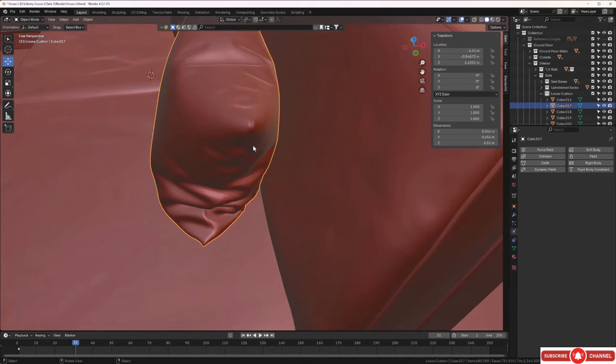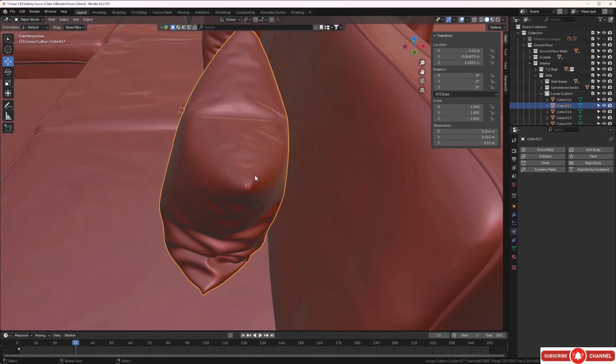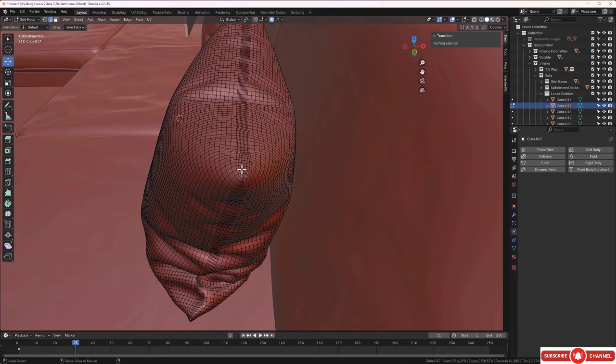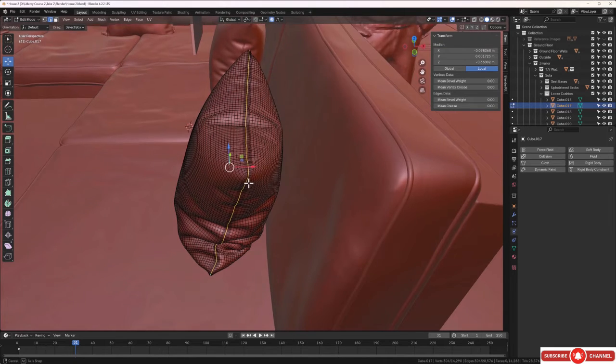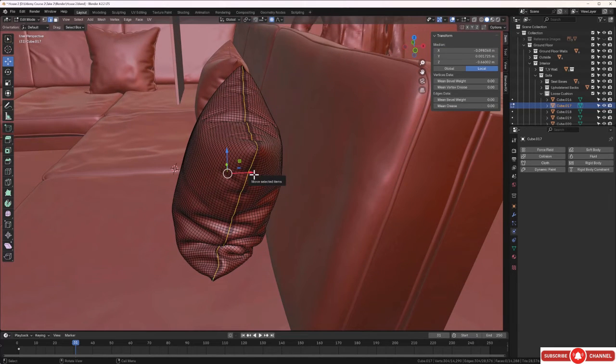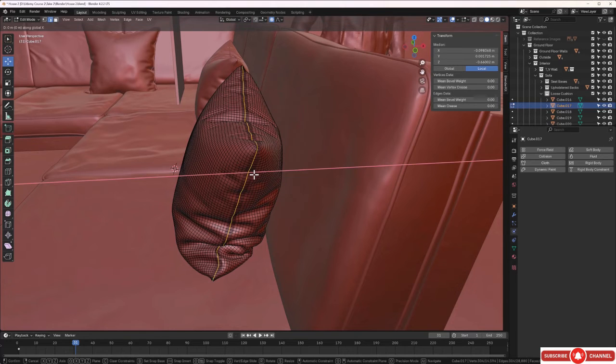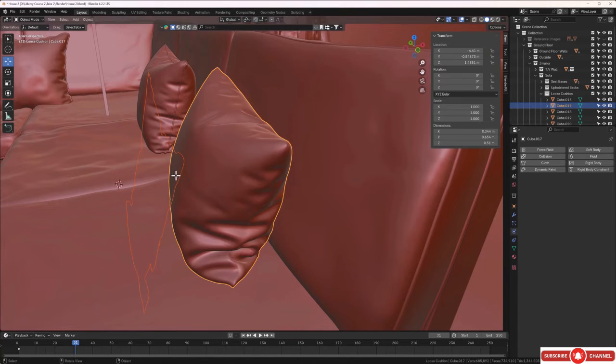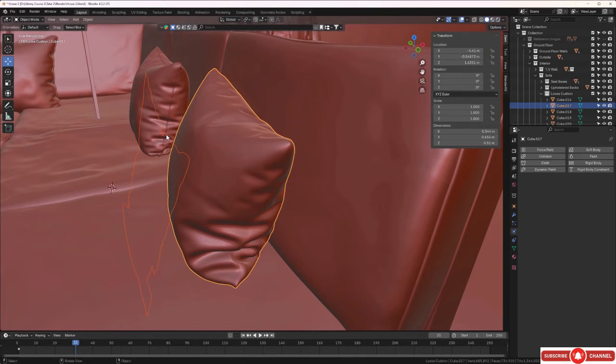And I'll go ahead and tap into edit mode with this. And I'll make sure edges are on. And I'll hold Alt and grab this edge maybe here like this. I'll press Shift D and X and bring this copy forward in this case like this. I'll press P and I'll separate by selection and tap out of edit mode. Okay, now I've got this one like this.